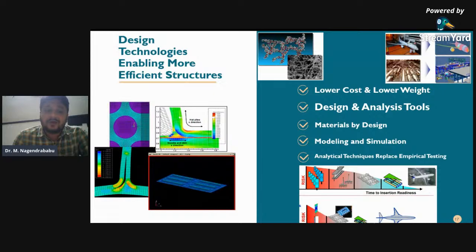Also important, composite components can be formed into complex shapes that for metallic parts would require machining and creating joints. Preformed composite components aren't just lightweight and strong. They reduce the number of heavy fasteners and joints, which are potential failure points within an aircraft. In doing so, composite materials help drive an industry-wide trend of fewer components and overall assemblies, using one-piece designs wherever possible.